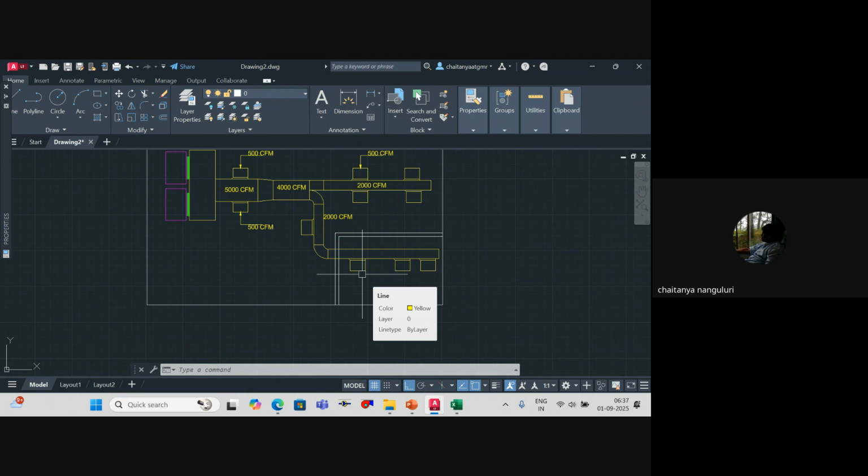The civil block work can definitely withstand fire, or it has to be done with fire rated gypsum, if not. And the door will also be a fire door, not a normal wooden shutter door. It will be a fire door which can withstand 120 minutes, and we take test certificates for that.